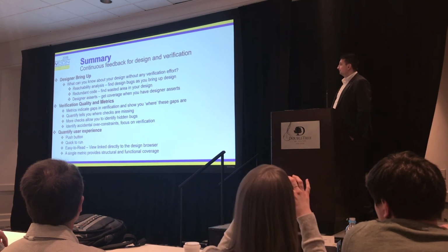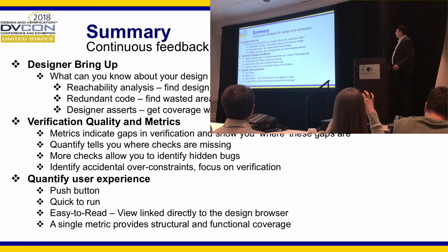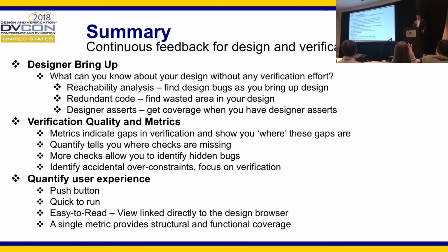So in conclusion, I just want to reiterate once more. We were talking about designer bring-up and using Quantify right from the get-go to measure your verification effort. We can do reachability analysis, redundant code. We can handle designer asserts, so it's already good. If your designer is willing to put some inline assertions, you already get some verification metrics as soon as you get the design, before you start writing these assertions yourself. And these metrics can indicate gaps. Quantify will tell you where you have checks missing, where you have over-constraints.